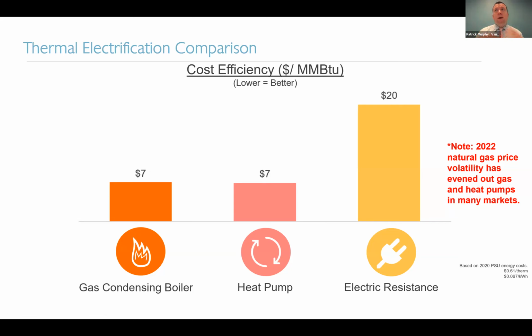And so the paradigm that we've always thought about, at least for the last 20 years, of energy conservation measures needing to pay for themselves, having a payback, doing a life cycle cost analysis, now maybe is not the right approach here. It's about how do we get to a zero carbon option the most cost effectively, and that's going to be a heat pump, but it's not necessarily going to pay for itself compared to the gas boiler, because gas is just frankly cheap.